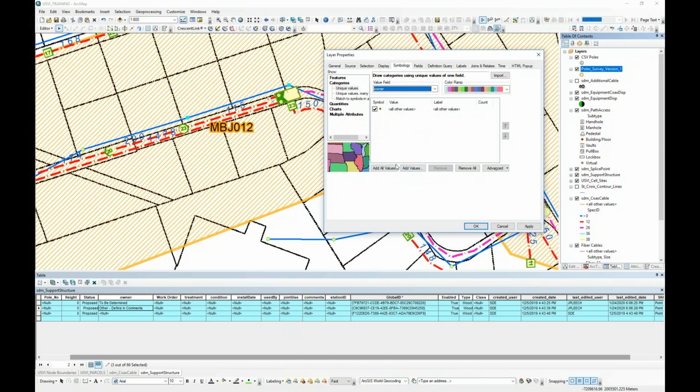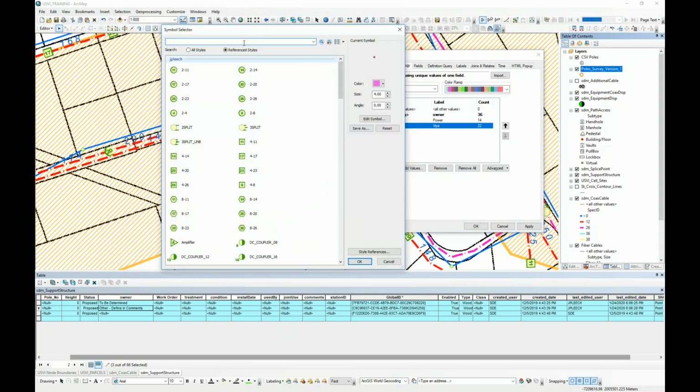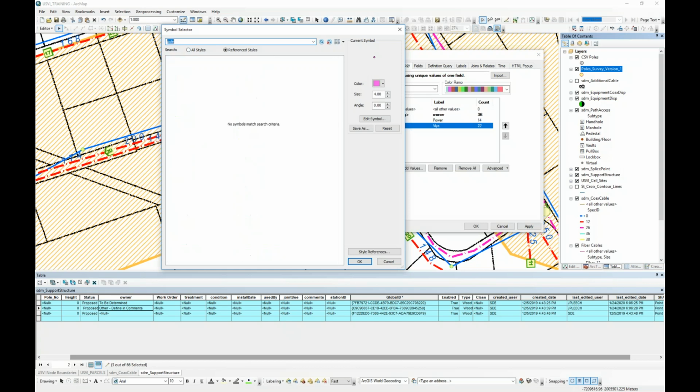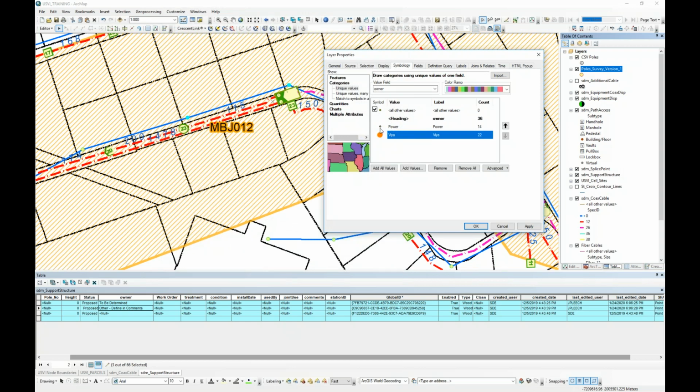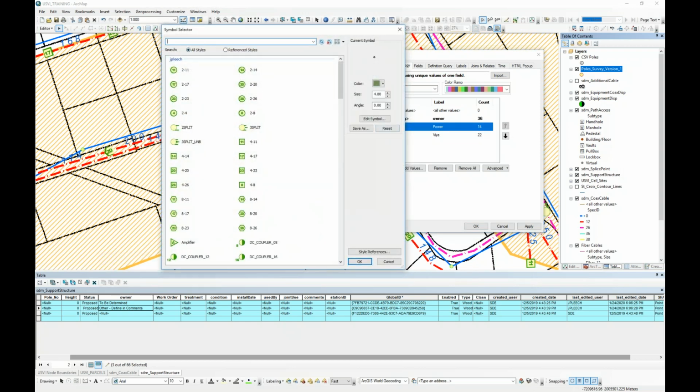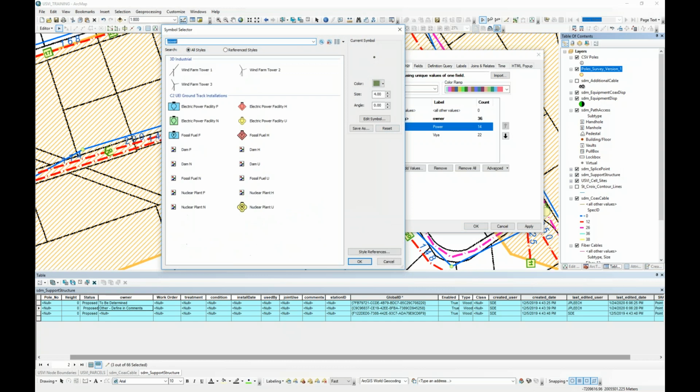So you're changing to the owner. It doesn't know what that is, so you need to add the values that you said you're selecting. So you have via, you have power. Those are different ones. So for via, you want to change it to pole. Whatever you want. Change it to electrical pole, exterior mounting light pole. So the via ones are orange. Your regular power are something else.